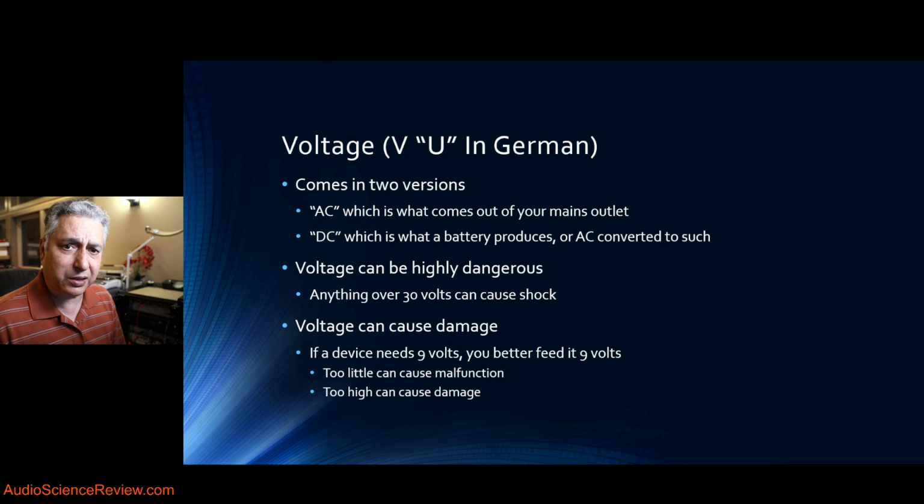Key thing about voltage is that it can be quite dangerous. Standard sort of threshold of when it starts to become dangerous is 30 volts, although, I think 40, 50 volts probably okay, but will give you a jolt. And as it gets higher and higher, you can get serious shock and or die. So voltage is critical to understand that concept. If you're going to get inside of audio equipment, take the top off, it's important to identify whether it's a high voltage device or it's low voltage, and I'll talk about this a little bit more later on.